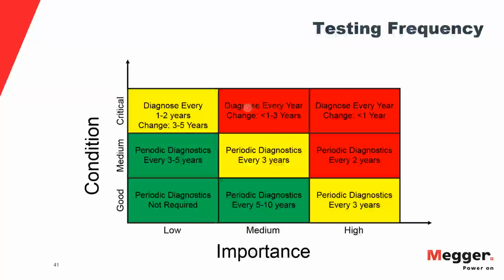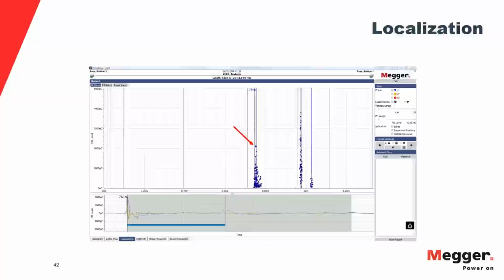So when we have a partial discharge event in the cable, it induces a signal into the cable, and that signal travels in 2 directions. One of the signals travels directly back towards my receiver, towards my measuring equipment, and one of the signals heads towards the far end of the cable. Once this one reaches the far end of the cable, it hits the end and it bounces back, and it starts heading back towards the receiver. The receiver picks up this initial pulse, and that's when it starts the timer, and it starts sitting there counting and waiting for this pulse to arrive.